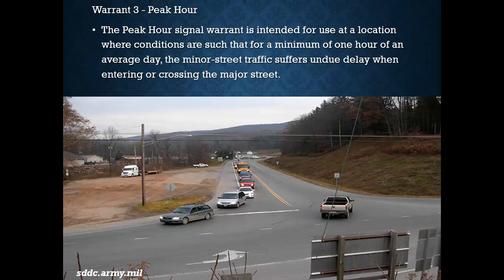In my country, Nigeria, there are certain peak hours, most especially within 7 a.m. to 8 a.m. in the morning in cities like Lagos. These are peak hours in the morning where we have lots of vehicles on the road. And warrant 3 is brought into the picture here to help know whether there is going to be a need to have a traffic signal at a particular point or location at an intersection.